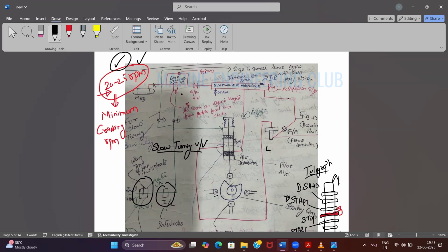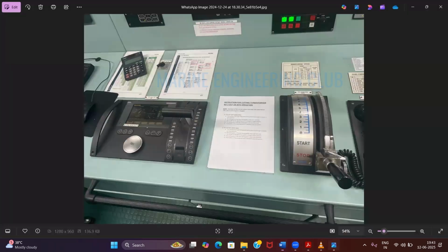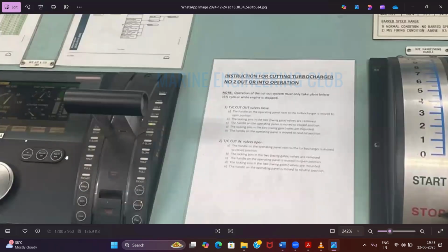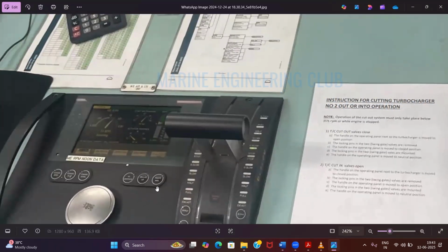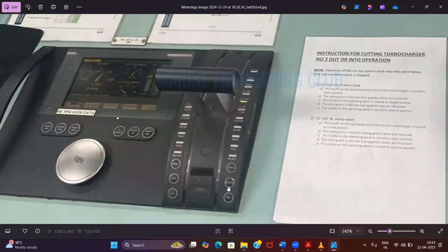So now you all are putting standby to your engines. You press standby? Yes sir. Okay. Here the figures are given over here, not very clear. But here my buttons are there for putting, not here, here. Right now it is on standby. Right. This is finished with engine. And this is for your once at sea. Okay. So these 3 buttons are there. Agree? So right now my engine is on standby and it is running at slow ahead at some RPM right now.